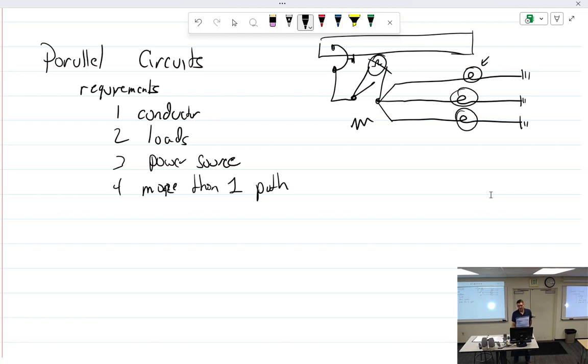Power the circuit and do what? Use Ohm's law to calculate the resistance. You'll be surprised at how much better that works. Check the voltage and use Ohm's law. Check the voltage drop. You will pick up ohms where you will never see them before.